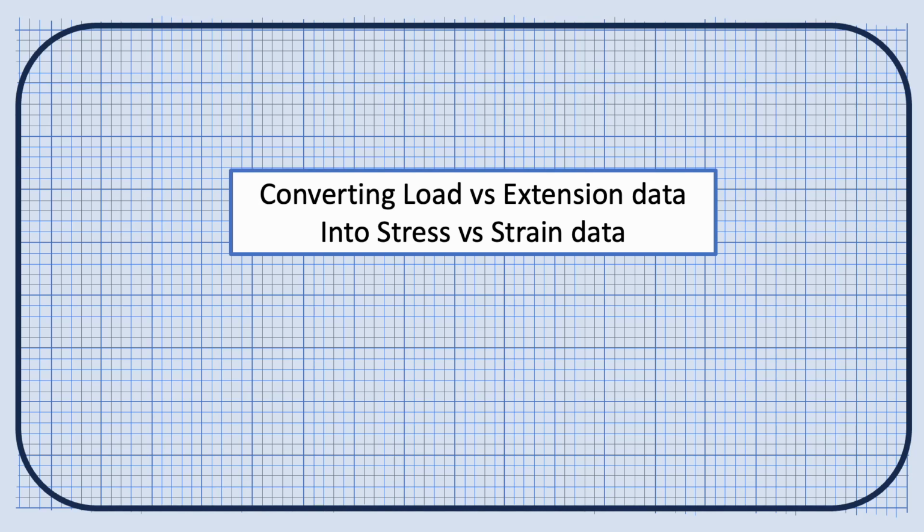All right, here is a presentation that I put together on how to take data that you get in the form of load versus extension on a tensile test and convert that to stress versus strain data so that you can calculate the modulus of elasticity and the yield strength, and if you want, the ultimate tensile strength.